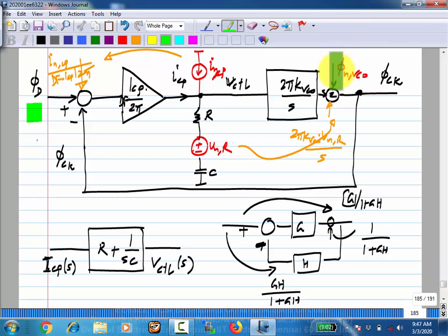So this is like negative feedback correction, right? Like noise cancellation. You add a noise here, and then you sense that, and then feed it back through this. Now, at low frequencies, whatever you inject here will be cancelled by whatever is coming out of there. At high frequencies, of course, this path cannot cancel it, right? So there is always a bandwidth limitation for cancellation.